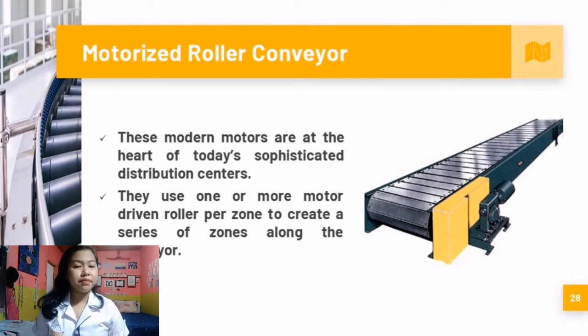The design is similar to a gravity conveyor with the addition of motors. The number of motors is dependent on the load to be moved and the overall design of the system. The connection between the rollers can be a chain or a belt. In some systems, there is a sensor that starts and stops the motor to avoid pieces getting packed together.